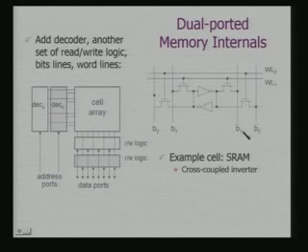Similarly, B1 and B1 bar and read the data from this cell. So, I have now got dual ported read access from SRAM. In fact, dual ported memories are very common in SoCs and on-chip memories for various DSP processors, as well as registers. The register bank implementations are also through this kind of dual ported SRAMs.